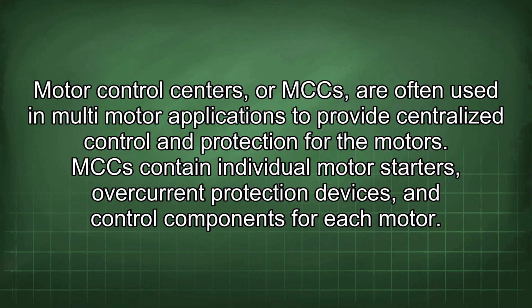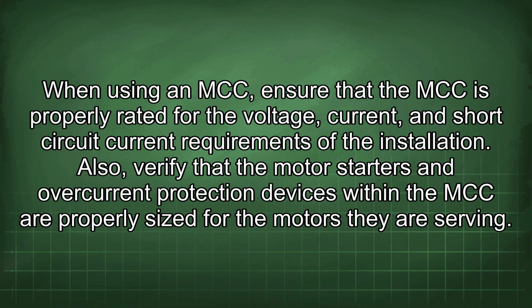Motor control centers, or MCCs, are often used in multi-motor applications to provide centralized control and protection for the motors. MCCs contain individual motor starters, overcurrent protection devices, and control components for each motor. When using an MCC, ensure that the MCC is properly rated for the voltage, current, and short-circuit current requirements of the installation.